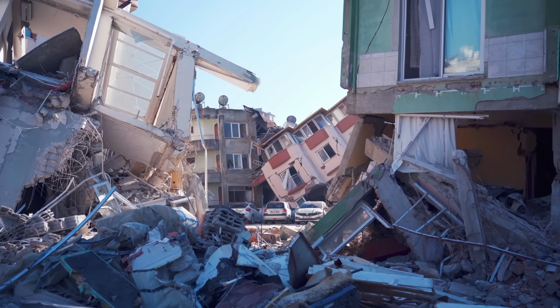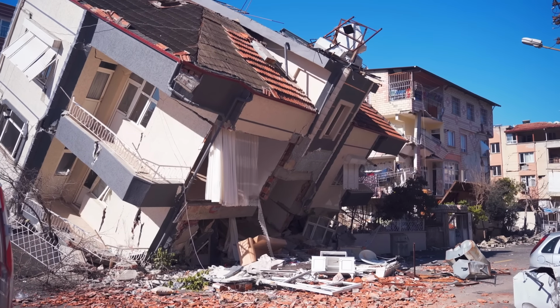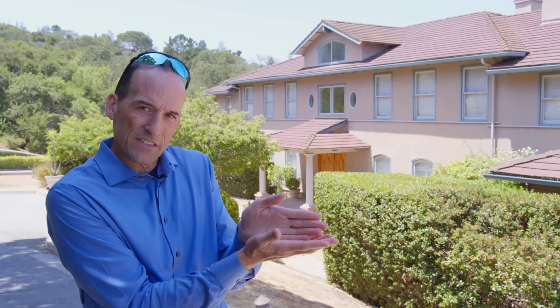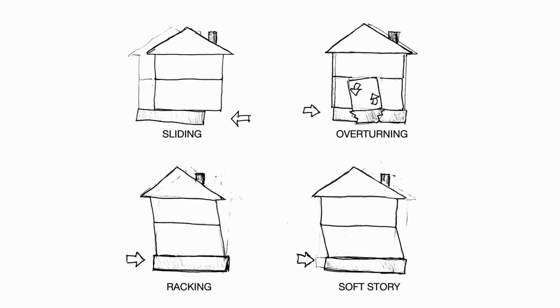Here's the problem: on a house that was built 35 years ago, you have to think about the additional mass, the additional material you put on the roof and on the walls. And in earthquake country, like we are here, we have to think about how that material makes it more difficult for that house to stand in an earthquake. So what happens in an earthquake is you have a house and then the earth slides. The earth is actually pulling against the foundation, and the structure of the house has to drag the rest of the house with it. So what happens if the house isn't dragged with the foundation? The house falls off of the foundation or the house collapses like a house of cards.